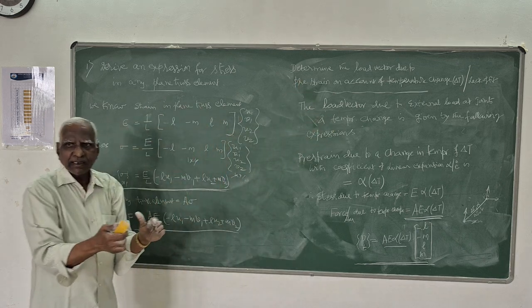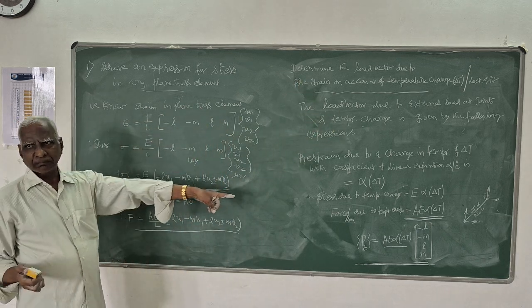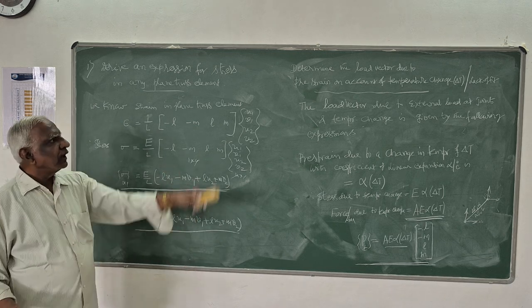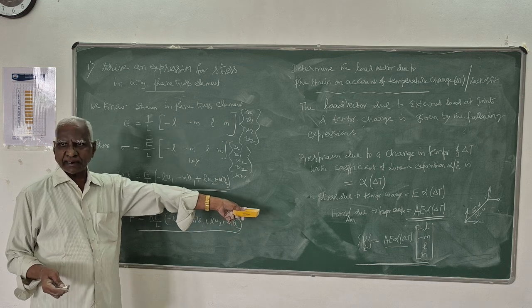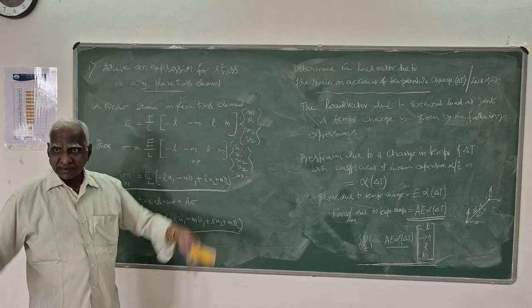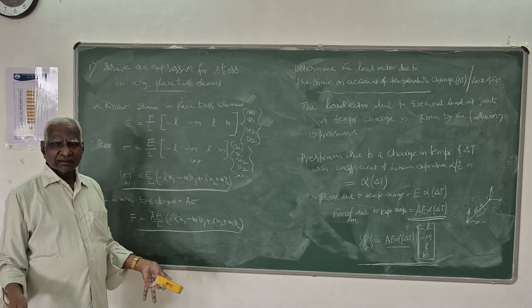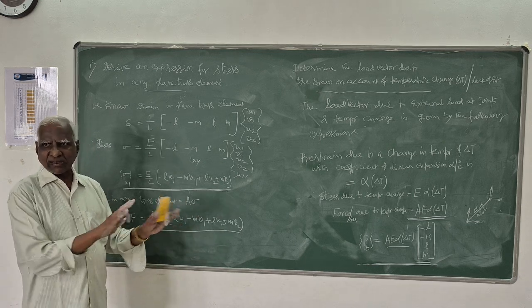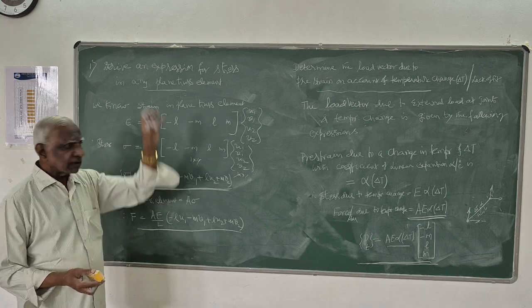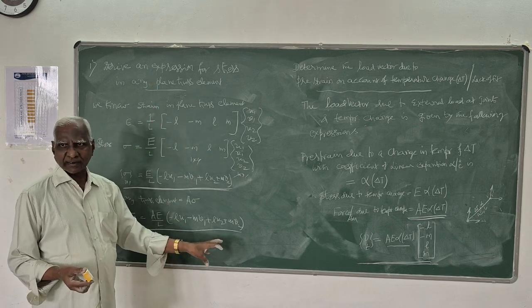How to find the equivalent load other than external load? So the external load will change: load due to temperature change, load due to lack of fit, load due to self-weight, as well as any other load. Surface load is not coming; that we will take up in the beam problem. That is the right hand side load vector.